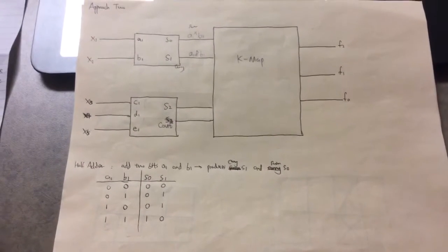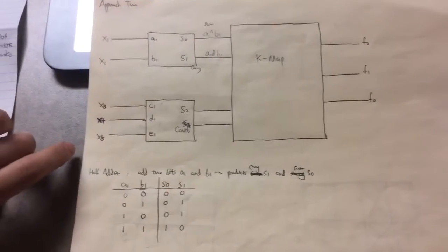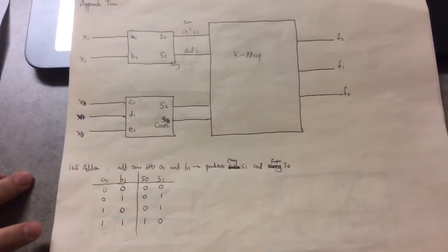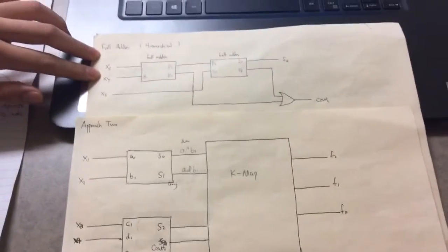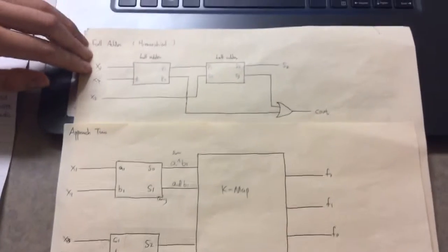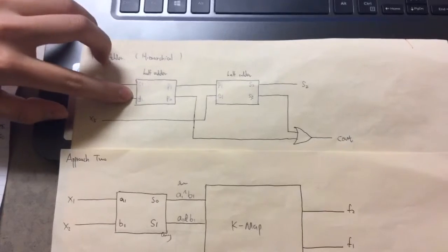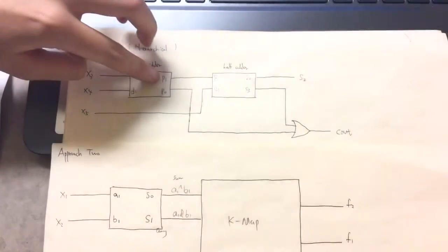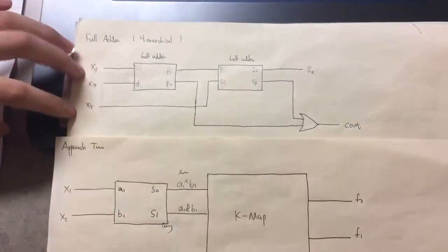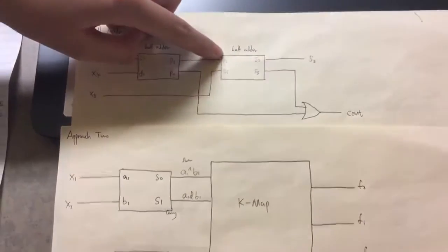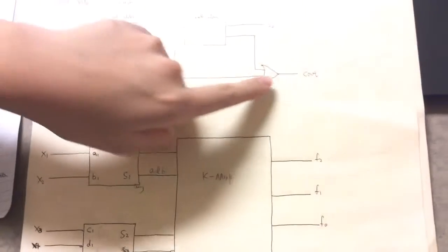And for the set of 3 switches here, I need to use 2 half adders connected to each other and draw the diagrams of the 2 half adders. Firstly, I put x3 and x4 into the first one to get a P1 sum and a P0 carry. And then add x5 into the second one to get a sum S2 and a carry C out.